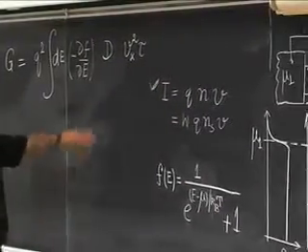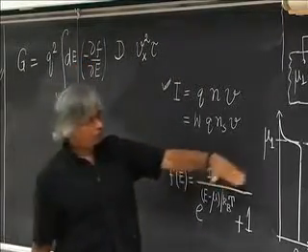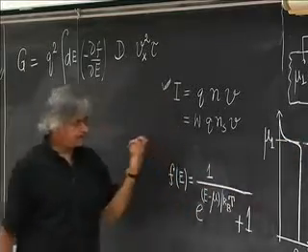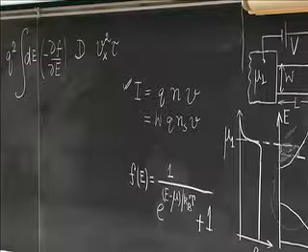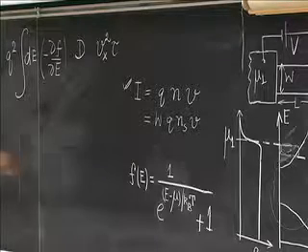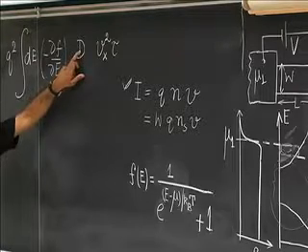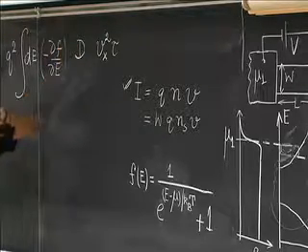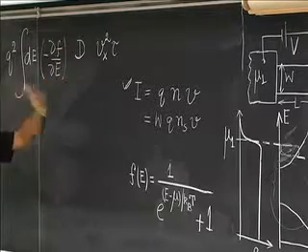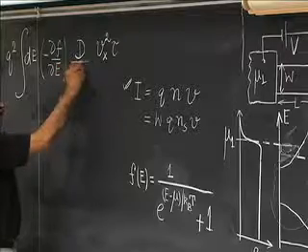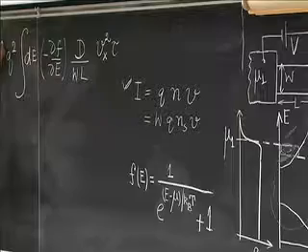Okay. Now, this F is basically what you'd have at equilibrium. That's the F that you use here. And this D is the density of states per unit area. So I'll usually define the density of states just per unit length, per unit energy, rather than per unit energy per unit area. So what we'll do is divide this by WL. And by the way, there's a W over L out here.